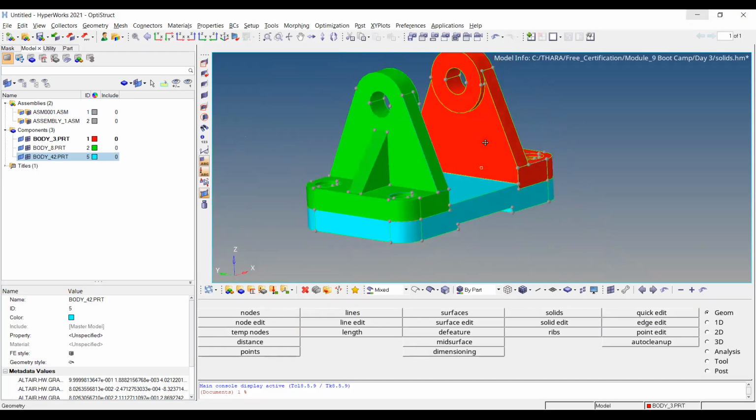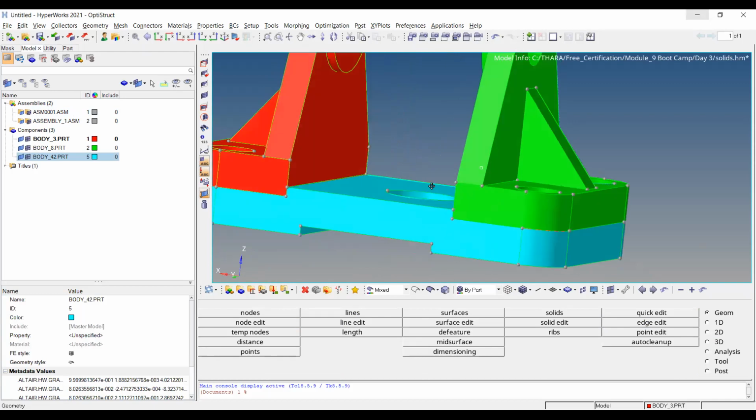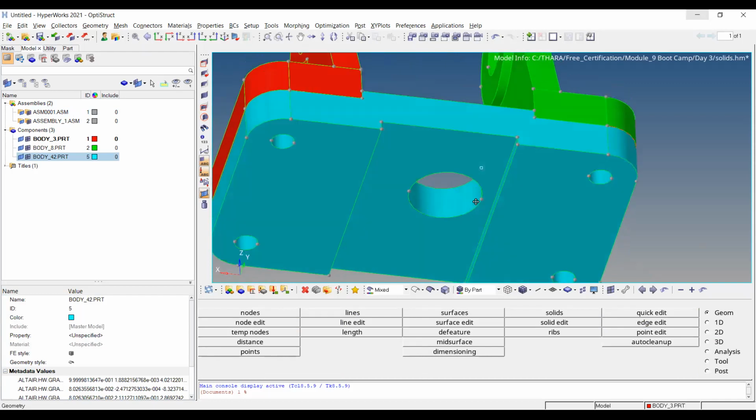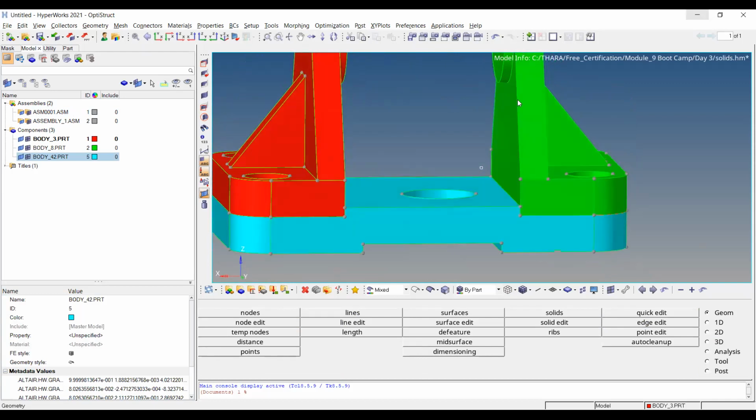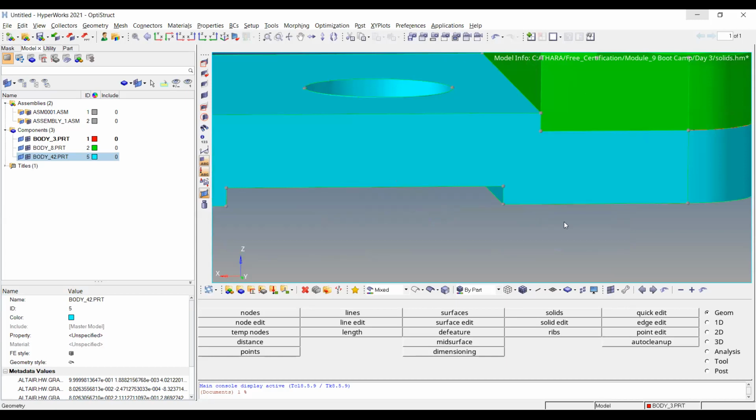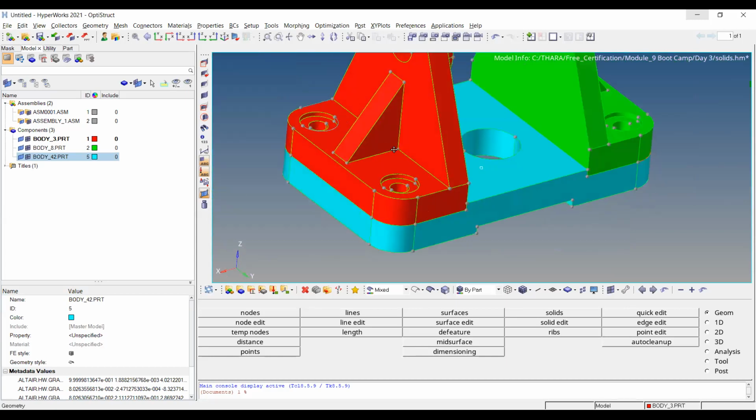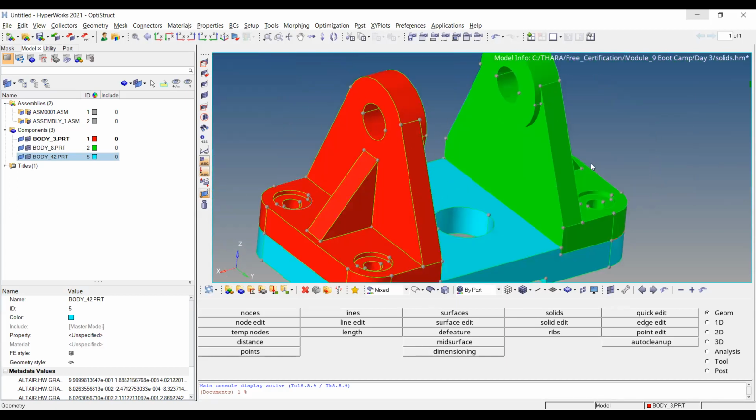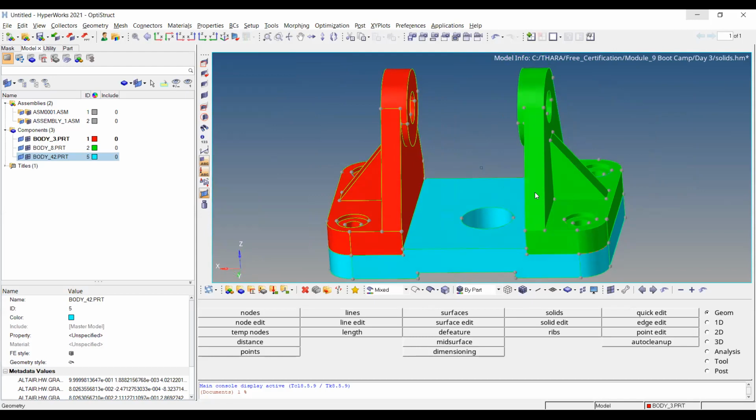Now, for the 2D meshing, we are going to carry on with it. If it is having a lesser thickness, we will extract a mid surface and proceed. But if the component is having a higher thickness like this, if the component is like this, then what will we do? We will go by creating the hexa elements, or we will go by creating the tetra elements.